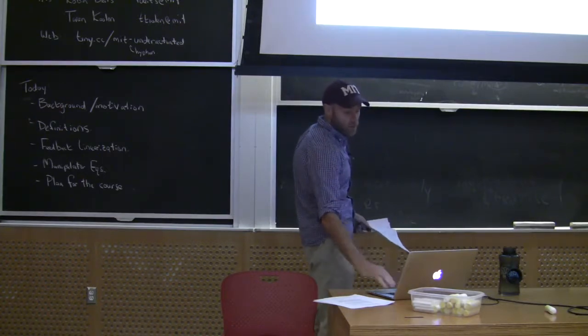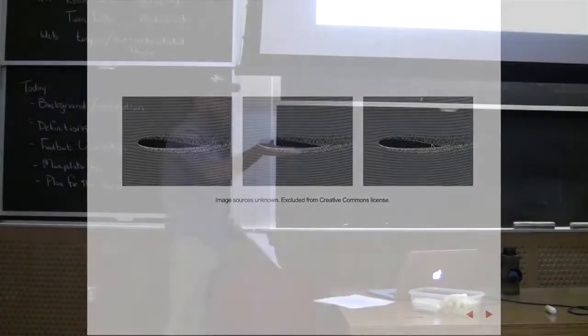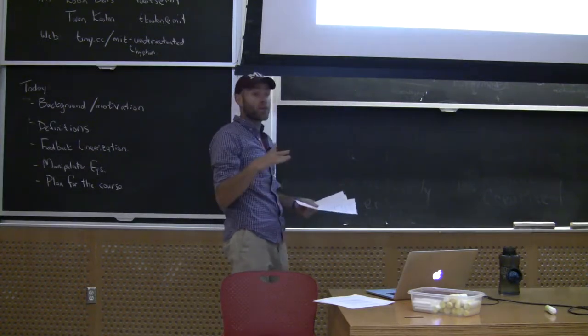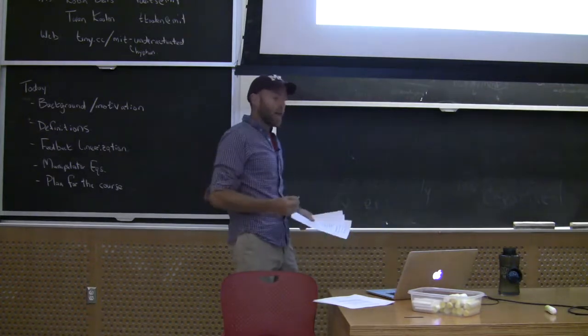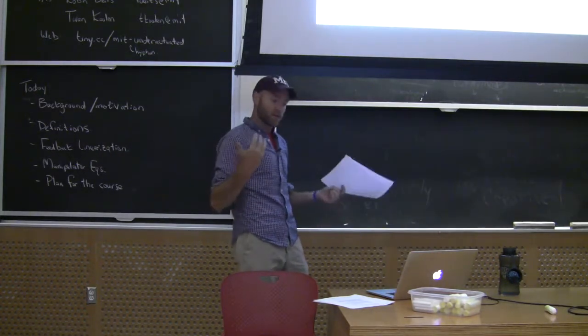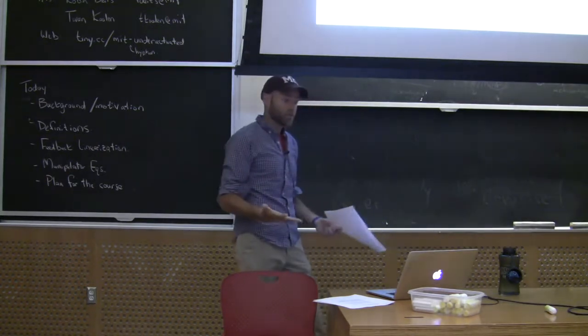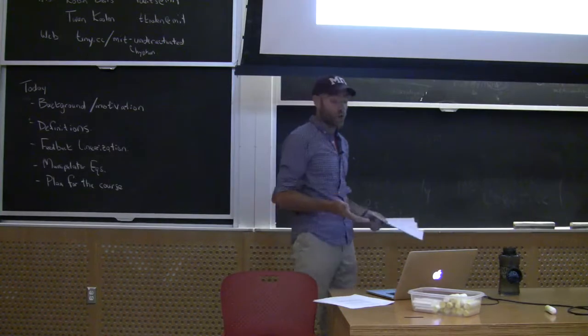And then if somehow the images didn't actually update, that's too bad. This one's supposed to be a stalled angle of attack, okay? If you raise your wing to too much of an angle of attack, the air basically can't bend around the wing. It will separate, and you'll get a vortex shedding phenomenon. And what happens in the modeling, if you care about designing a control system, is the system becomes very nonlinear, okay? And effectively, we haven't had good tools to control those systems.